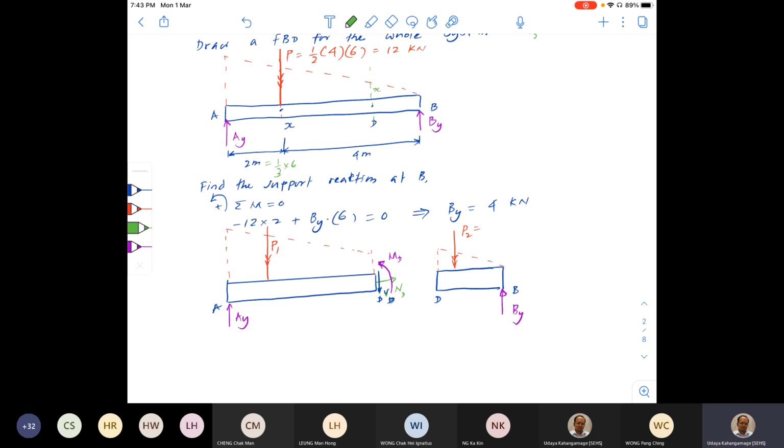So in AD I mark ND away from the cross section, right? Now in the other part, it should be in the opposite direction, so that once you put them together they cancel off, right? So if you don't cut, there are no forces, right? Once you cut, only these forces open up, and then the shear force should be marked in the vertical direction here, opposite to VD, and your moment should be in the opposite direction too.